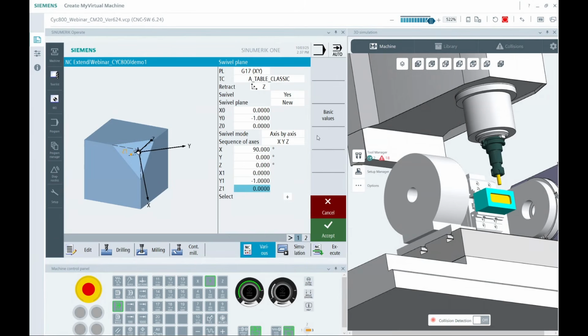Had I wanted to do an additive, then I would have to back everything out, right? So I would probably have to stack this in 2, or I can shift my 0 down and flip it 180. It gets a little confusing if you think about it, because it would be rotating in relation to this last move, which is really a 180-degree rotation. So generally, I typically stay in new unless the position I can only achieve by stacking it on a previous one.